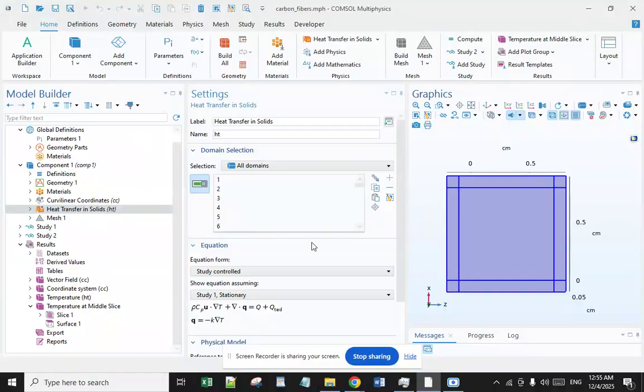The dip at the end of the C_p graphs indicates the end of the test, a little before 140 degrees centigrade. The silicone rubber seems to have the highest C_p value, which agrees with the literature.